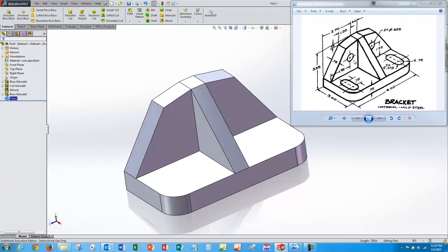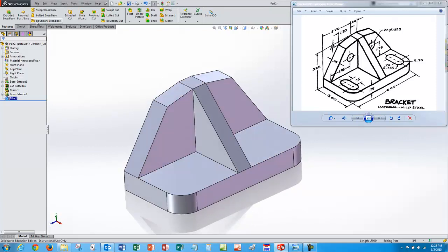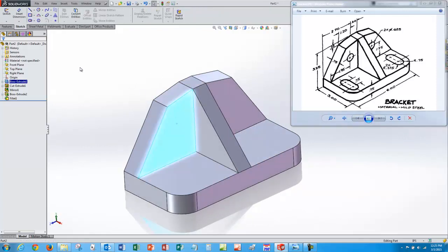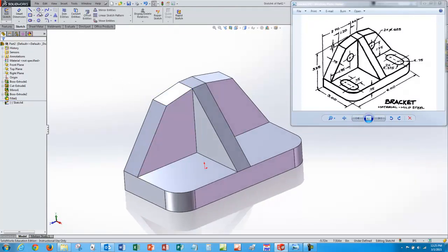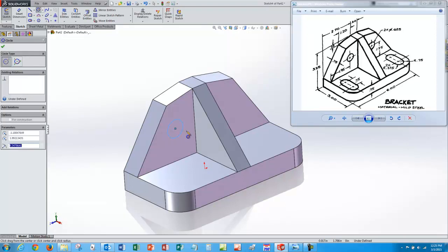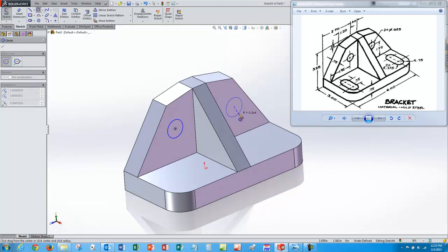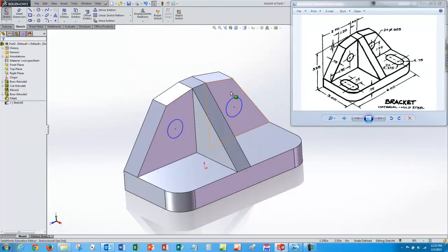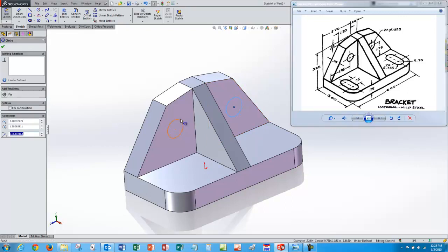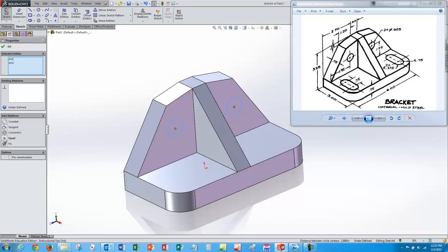Now let's make these holes. I'll just do 2 holes, 2 circles on this face. I'll extrude those through. So let's go to sketch on this face. Hit the sketch button. Now I just freehand 2 circles in here. One here. One here. And again, I want to take advantage of geometric constraints. Select that circle, control click this circle, add an equal constraint, approve that.